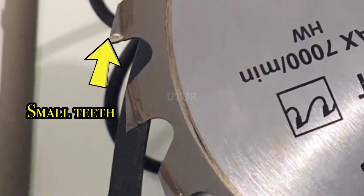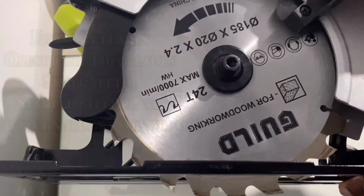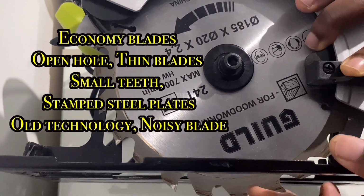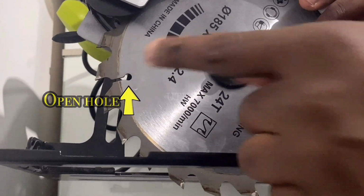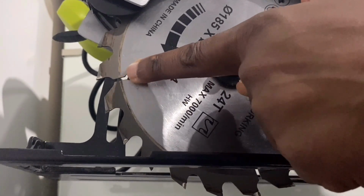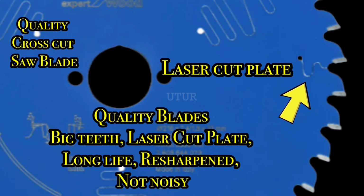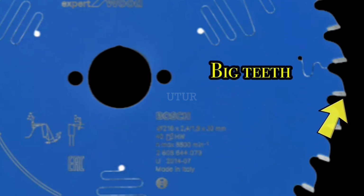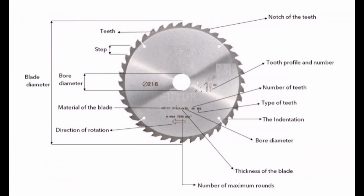Economy blades almost always have a thin stamped steel plate with expansion slots that end bluntly in open holes, which is what we've got here. The open hole exudes or signals old technology and a noisy blade, whereas good quality blades have a laser cut plate, as you can see here, and the length and width of each tooth tip is bigger than the economy blades. The laser cut plates are designed for long life and the teeth can be resharpened many times.